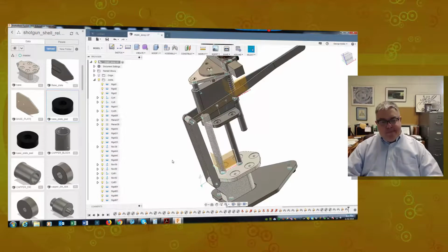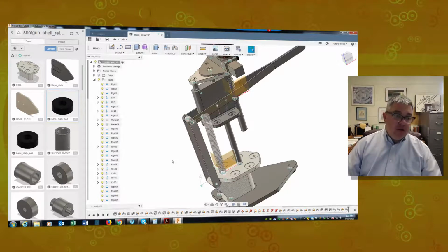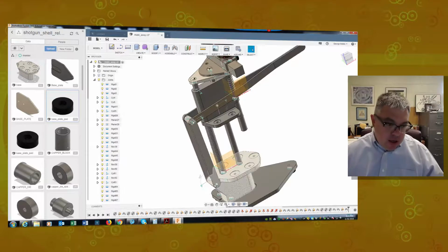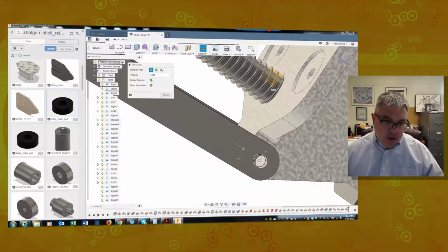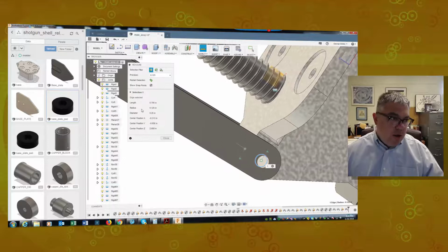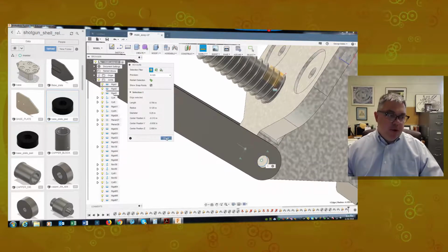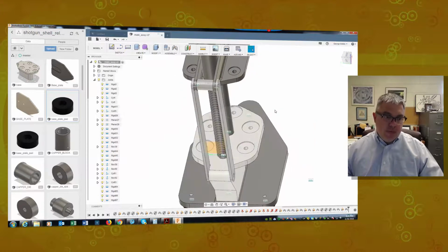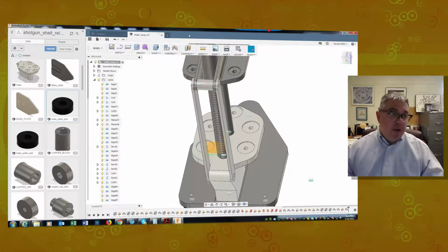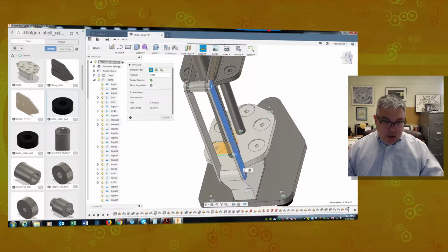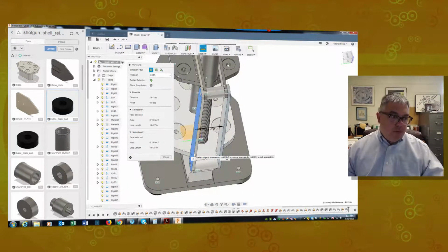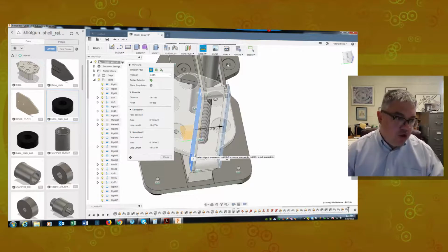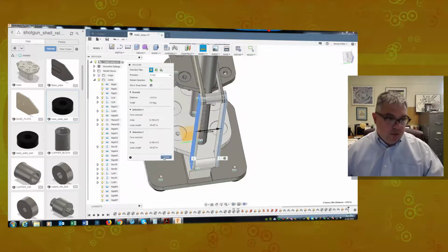So let's talk about putting together a bolted fastener, right? So obviously here with these guys, if I do this, that gives me a diameter of 1/4 inch, so a 1/4 inch bolt should be going through that. So if I want to put together a fastener, we'll say I probably need something, so maybe a 2-inch socketed cap screw with some washers.